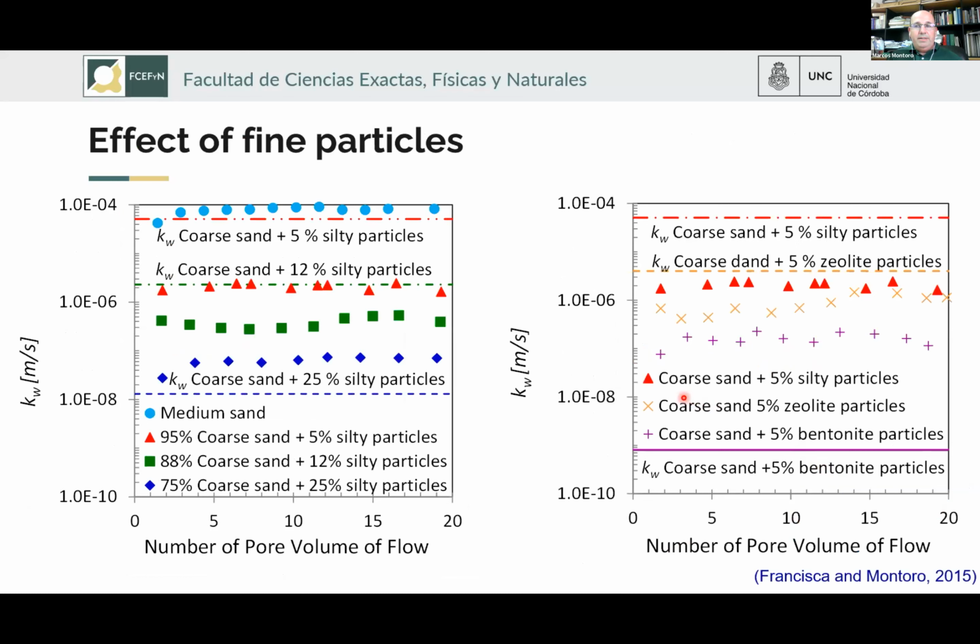Please remember that the soil particles were initially in close contact with the paraffin oil, so the electrical diffuse layers may not initially develop. While water displaces paraffin oil during the test, water starts to occupy the central part of the pores until they finally get in contact with the particle surfaces. The horizontal lines in the pictures represent the value of hydraulic conductivity of the clean specimens, measured with deionized water, as a reference value.